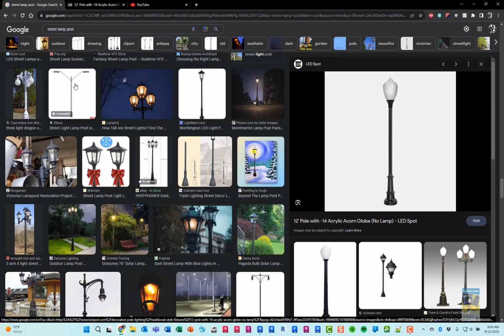So if you're dealing with building a family of this nature that requires more than one light source, then the way to approach it is to create a host family, which is the structural part of it, all the vertical members and the angled members and things like that, and then nest inside individual light source families and place them where you need them to be and lock them in position.